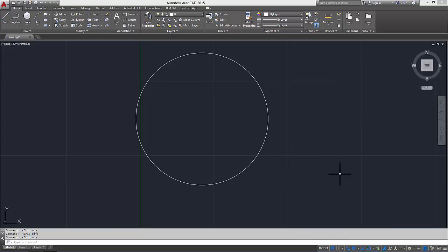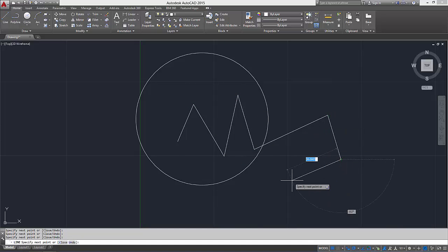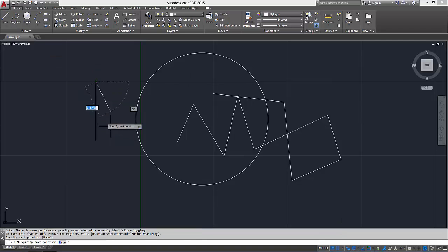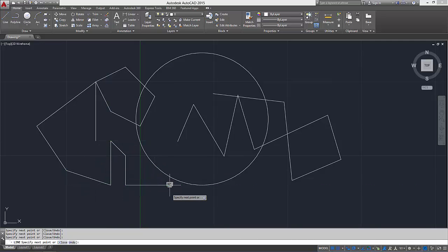So this status bar is really the one that you need to consider more than anything else. If you wanted to see the grid, then that's this thing. If you want to snap to the grid: if I was drawing a line at the moment, it's just going from wherever I want to wherever I want. So click, click, click, click to create the line. Hit escape to exit. If I turned on snap mode and started drawing the same thing, and I wanted to snap it to the middle of one of these boxes, I couldn't. I'm restricted to the intersections of the grid. Turn off snap mode, and then I'm free to create lines wherever I want. So that's the difference with snap mode.